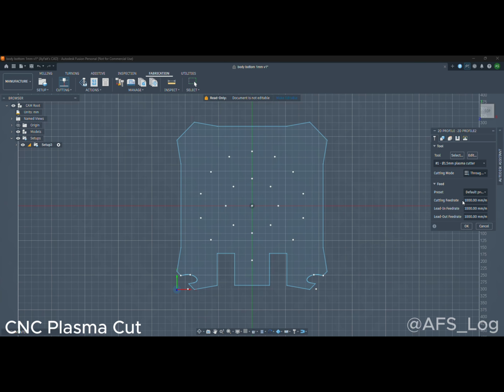Good. Now our geometry. This is where we are going. Notice that we have quite a number of profiles here. Like I've said in my previous videos, when I was talking about the shape library for plasma machines, when you want to program for your shapes, you should always make the internal cut before the external cut, which is very important. Here we have a lot of internal profiles. These little dots and circles you see here are the internal profiles. This is the external profile, which will be cut last.